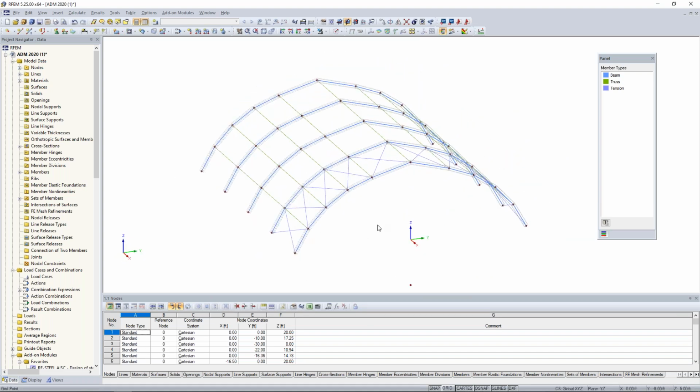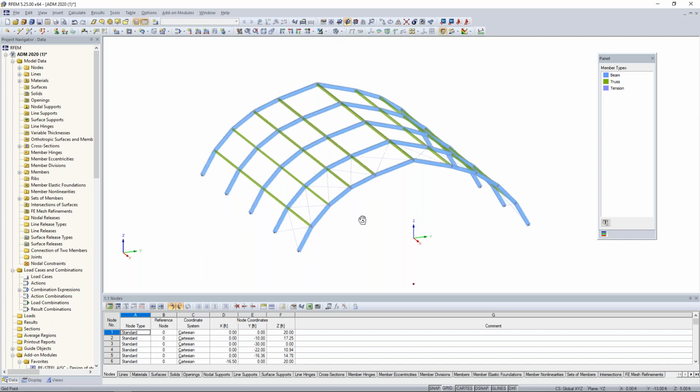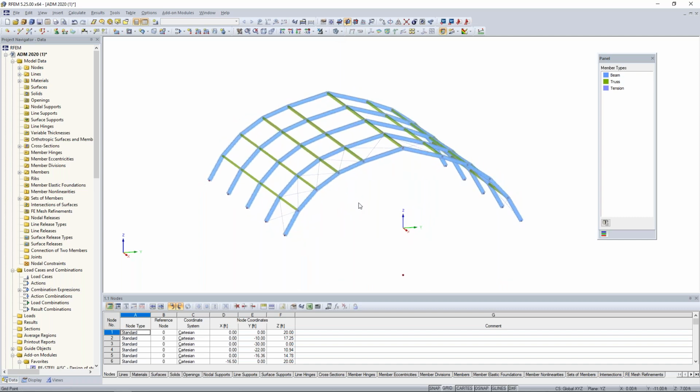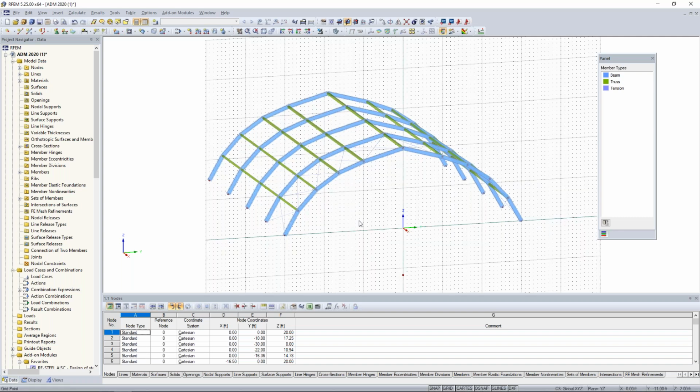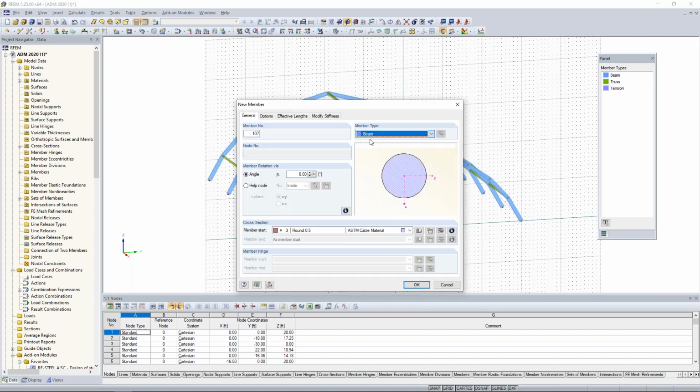All right, so we have all of these elements defined. The final thing to do for our supporting aluminum structure here is to go ahead and draw some columns and beams at the front and rear of the structure for additional support. So I'm going to turn on my grid element and we're going to draw a new member. This time the member type will just be a beam. We are going to select our 6x6 that we've already defined with the relevant material.